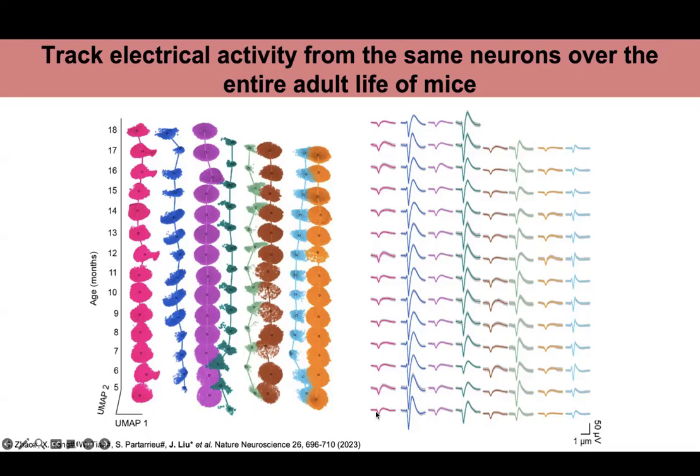You can see how stable we can capture those signals. For each channel, we can stably capture single-unit action potentials. After spike sorting, it's not just the amplitude of the signal that seems stable, but the waveform of the signal also shows stable, which suggests that we are not only stably capturing cell activity from the neurons over a long time, but maybe capturing the cell activity from the same neurons over this almost year-long implantation.